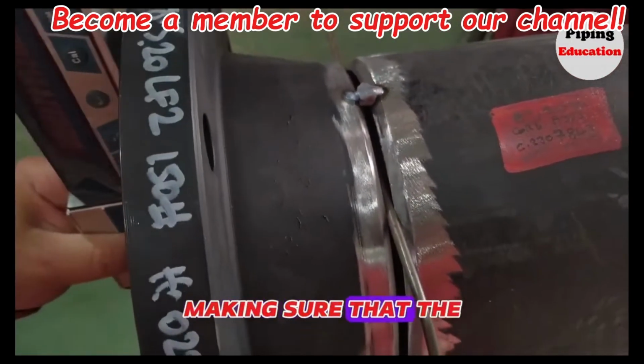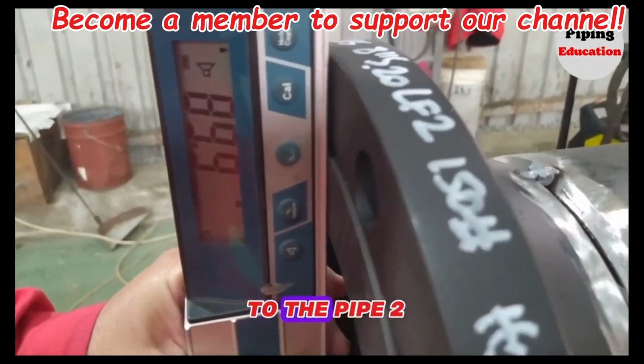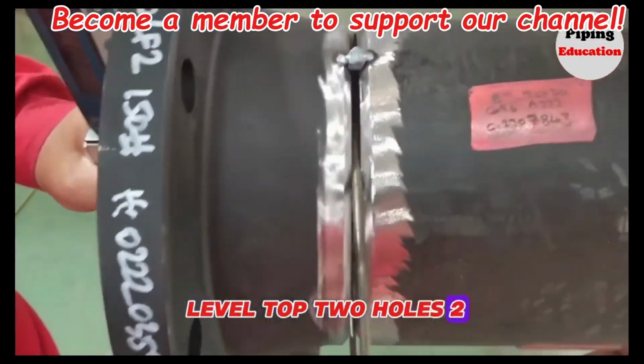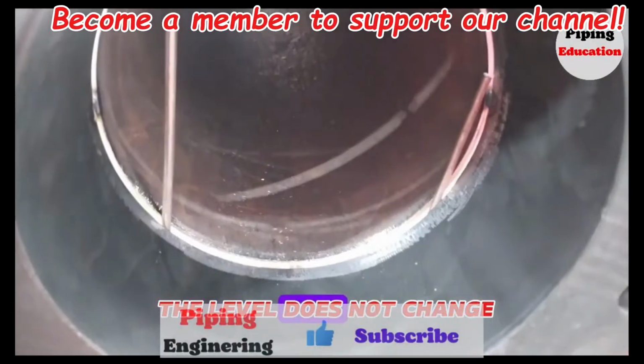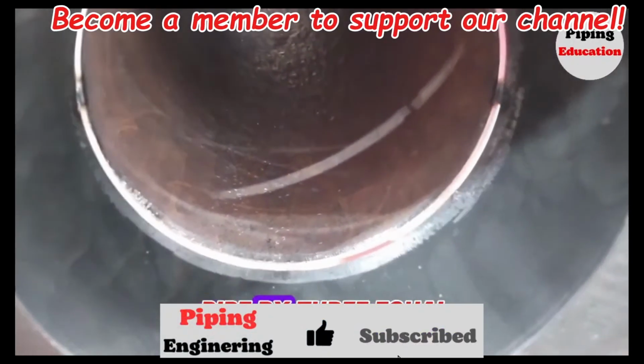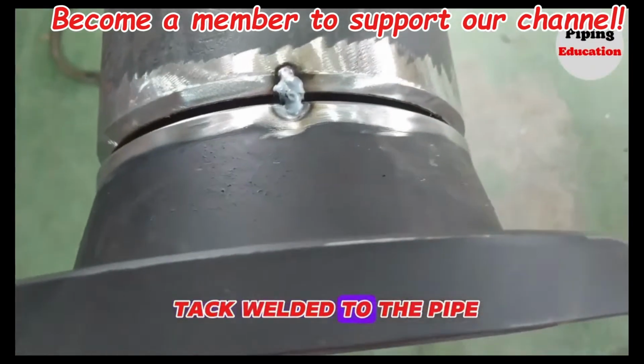After making sure that the top 2 holes are at the same level, we tack weld the weld neck flange to the pipe. And again we check the top 2 holes with the level. After making sure that the level does not change after the tack weld, we tack weld the weld neck flange to the pipe at 3 equal places. Now the weld neck flange is tack welded to the pipe.